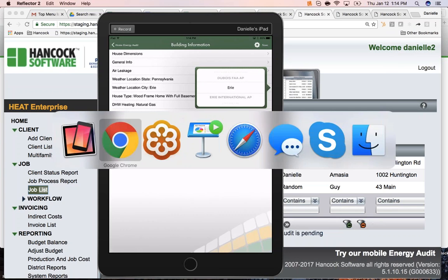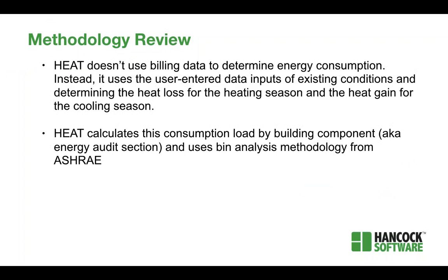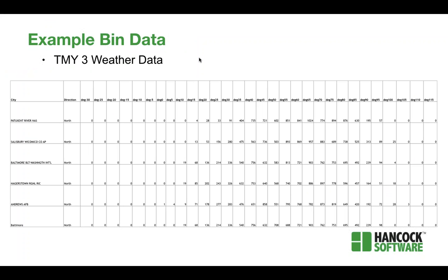So when you select this, Art, could you just briefly explain in the background, what is TMY3 doing with the data tables when you select that weather location? When you select the weather location, it's a bin to hourly 5-degree bin approach, which all tools use, and it captures the degree hours in those bins. So if you pick any given city, then that information is used to determine the heating and the cooling loads.